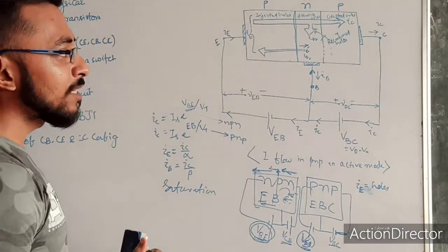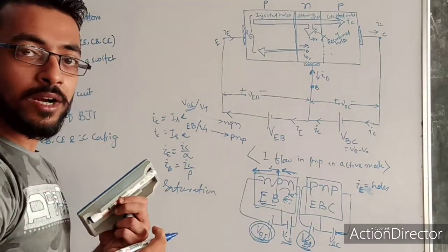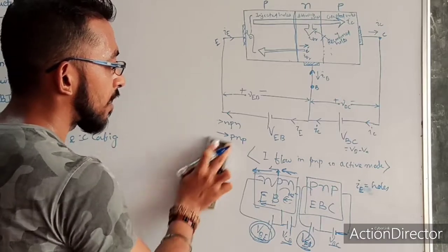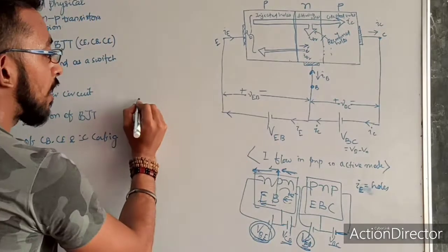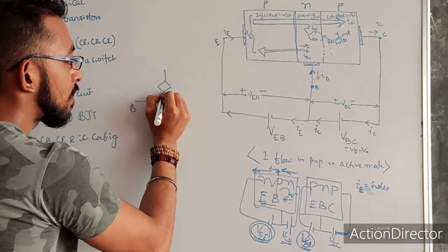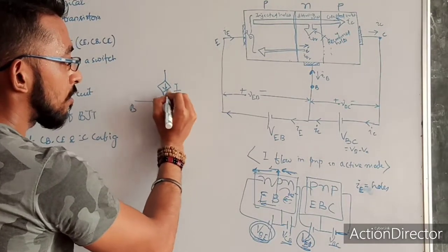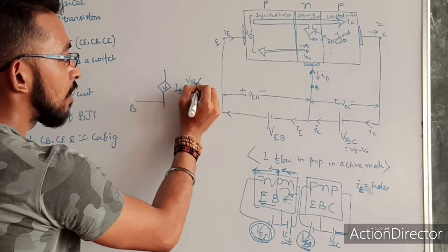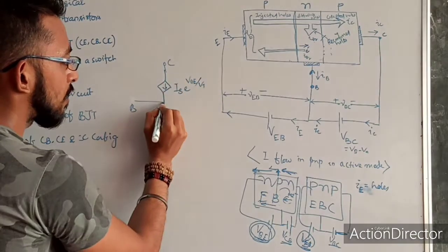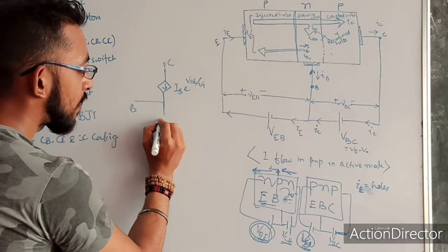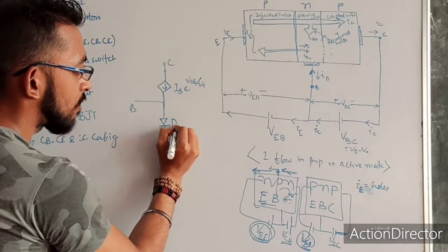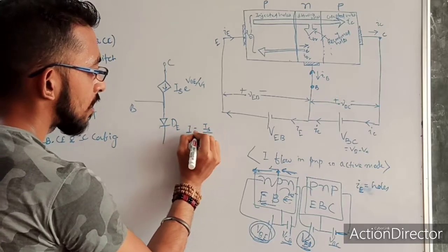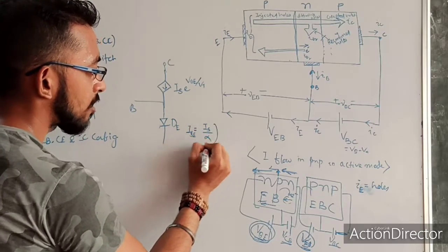And the last point is the circuit model that we drew for the NPN transistor. If you remember, I drew 4 circuit models for large signal. Like this is base, this is a voltage controlled current source whose value is Is e power VBE upon VT. This is my collector, and there is a diode DE which has a current ISE, which is nothing but Is upon alpha.